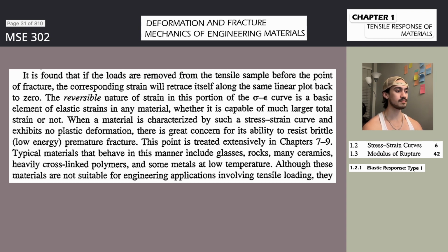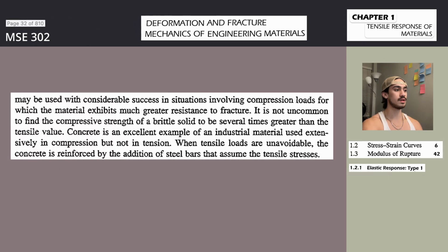1.2.1.2 Resiliency. The resilience of a material is the measure of the amount of energy that can be absorbed under elastic loading conditions, and which is released completely when the loads are removed. From this definition, resilience may be measured from the area under the curve in figure 1.1. Equation 1-18, where sigma sub max is the maximum stress for elastic conditions. Epsilon sub max is the elastic strain limit. From equation 1-7, we have equation 1-19.